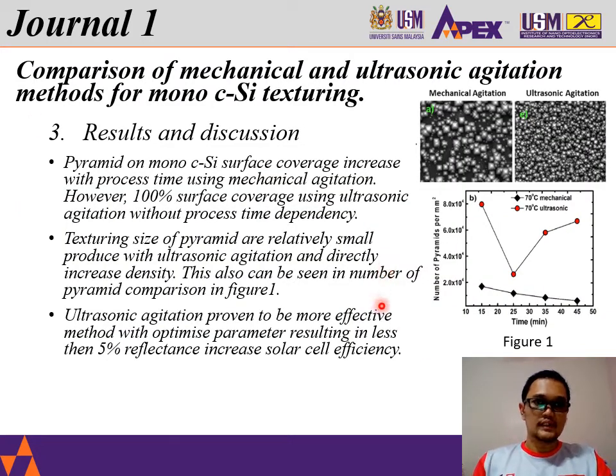Okay, the next slide is about the results and discussion from this journal. The pyramid shape coverage on the monocrystalline silicon surface increases with process time when using mechanical agitation. However, with ultrasonic agitation, 100% surface coverage was reported, independent of process time.